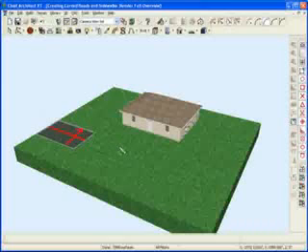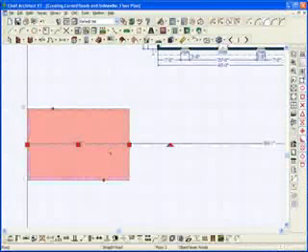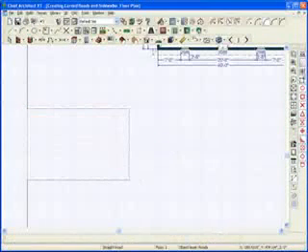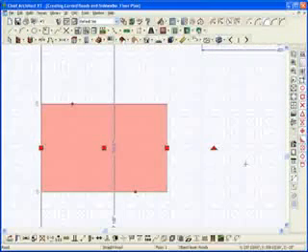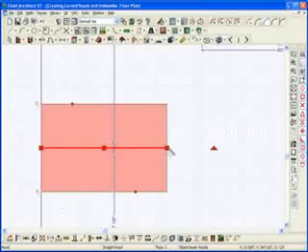That's a special polyline. That's what it does. But when you go back to the floor plan and look at this, you'll see there's no line there. But if I click on this road, notice those three handles that I get right here. They're the same three handles that I got for that CAD polyline that I drew on the floor plan before. So again, I could grab this end handle and bend this road by grabbing it.